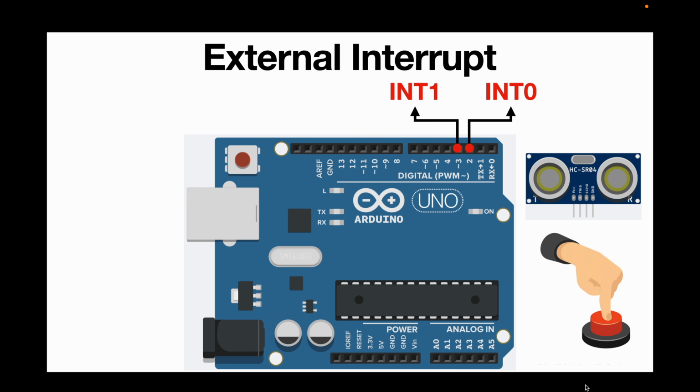An important aspect of the interrupt service routine is how it is triggered. There are three main possibilities that we are going to explore during the code development. An interruption could be triggered by a rising change on the pin, which means that the signal on the pin needs to change from low to high.